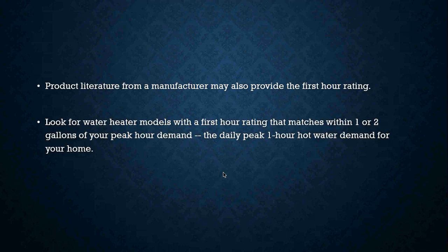When is that going to be in a home? That's probably going to be in the morning, right? Or maybe even at night when that person's coming home from work or getting up to go to work. They're going to get up, they're going to take a shower. Kids are going to be getting up, they're going to want to be taking a shower, hopefully. Or vice versa, they come home from a long day's work or from school and get into that shower. They're going to use all the hot water at that point. So we're going to size a hot water heater to handle or match that peak hour rating, or that first hour rating, that we calculated for.